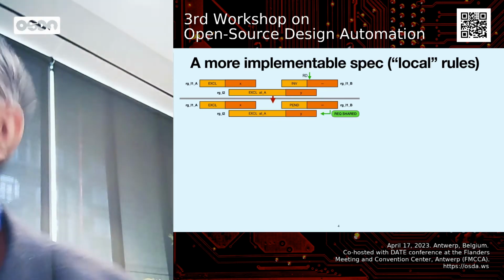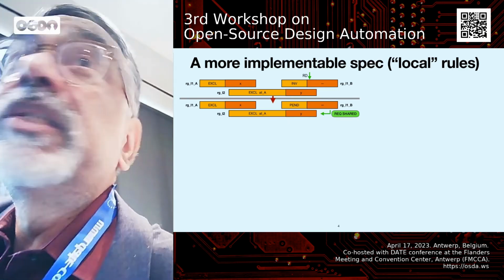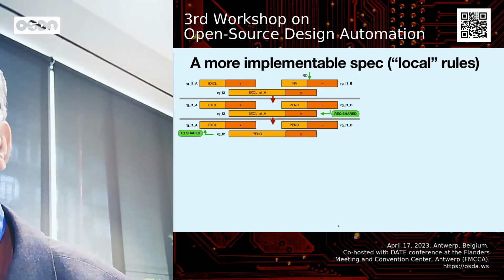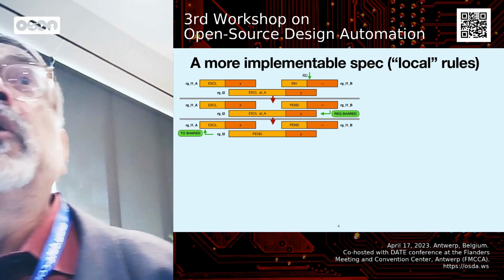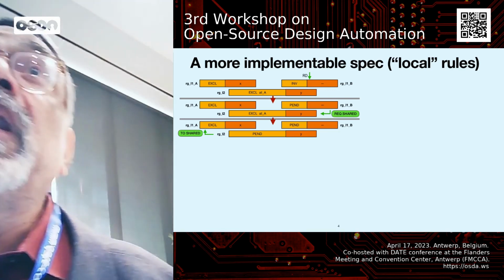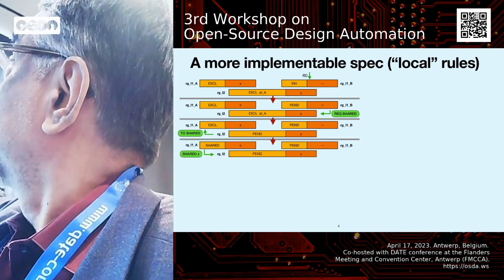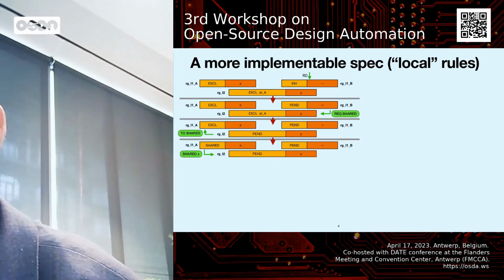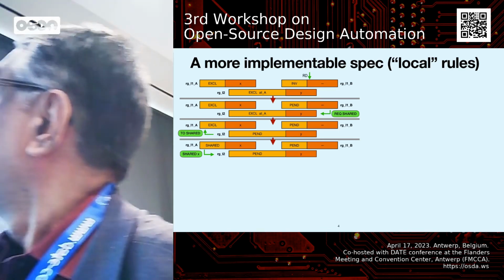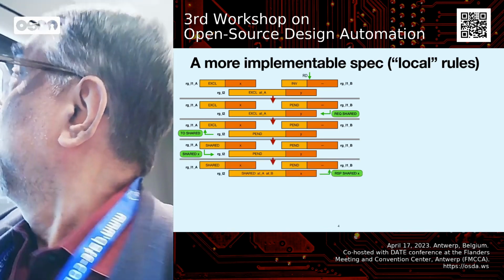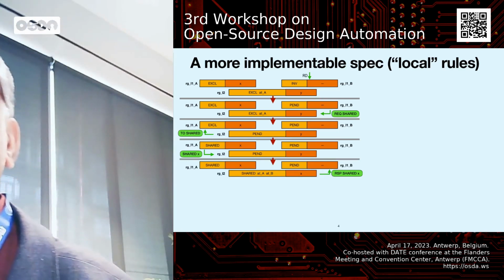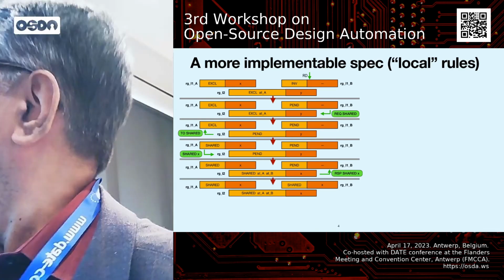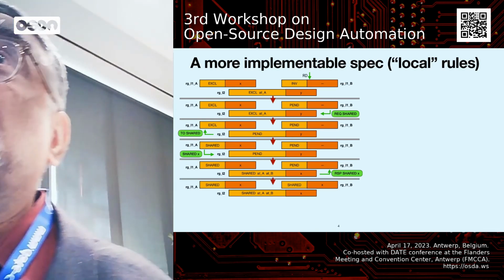So when we see this initial state, we send a shared request to L2, and we go into a pending mode on B. When L2 sees the shared request, it sends a downgrade request up to L1A, saying please get back into shared mode, and it also goes into pending mode. When that sees the shared thing, it goes into shared state, returns a shared response, and says here's the new value X. When the L2 gets that, it goes into shared mode and sends acknowledgement back to B saying, okay, you're shared. And finally, B itself can go into shared mode.